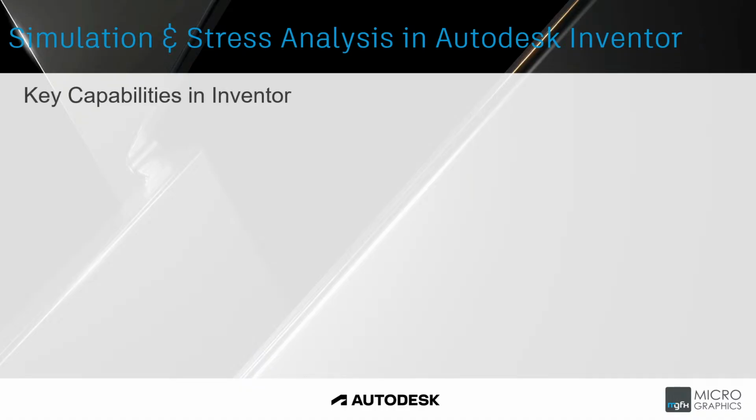The key capabilities in Inventor: it is your stress analysis environment. Now this can perform, for instance, static stress analysis on your parts or assembly, where you apply your force, your pressure, your constraints, and loads to see how the model deforms. You also will get visual results such as your stress distribution or your strain, even displacement, and you can set your different safety factors.